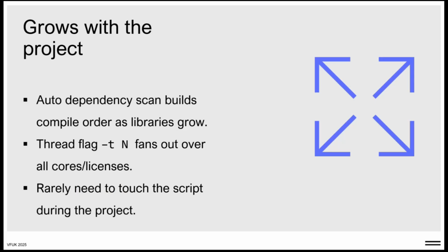HDLRegression is well suited for small and large projects, and its simplicity is also its strength. The test suite is controlled by the tool, meaning you do not have to remember to make updates when adding new files, and all is simulated. Using wildcards with the add files method in the regression script ensures all files are included. Often you do not have to update the script during the development of the project.